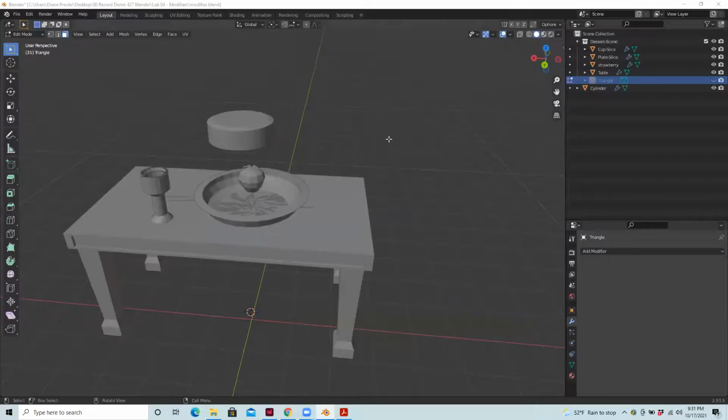The next step is going to be kind of interesting. I want to cut a piece out of the cake. And there's a modifier that can actually create holes or kind of merge shapes together. So this one will be a few steps. First, I want to go ahead and find the triangle in the scene collection and make it visible. And this is a flat shape right now, and we're going to extrude it to give it thickness.